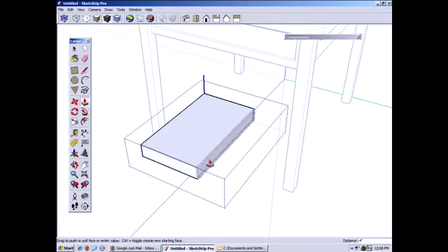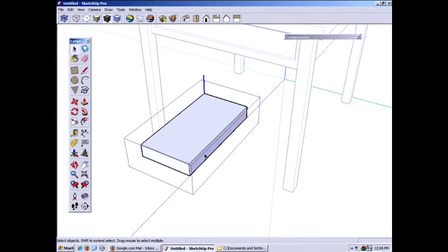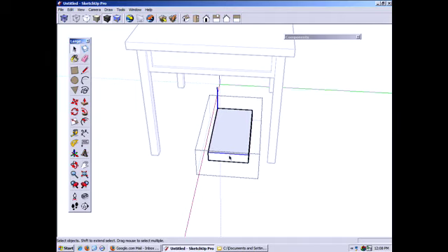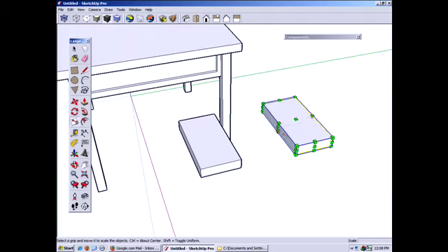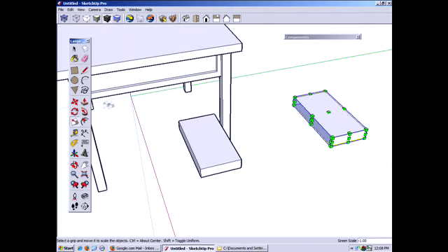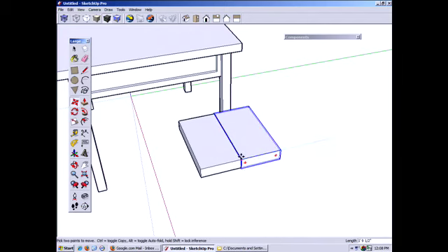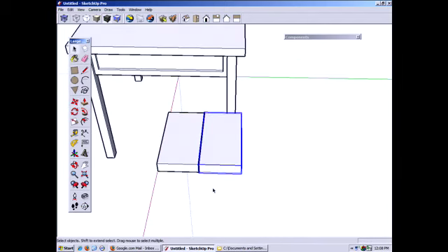And in fact, why don't I pull this back? Right from the start, I'm going to delete that surface, take this component, copy it, mirror it, bring it back. At this point, I'm not going to worry about hiding those edges yet, because we're still in the point of building.